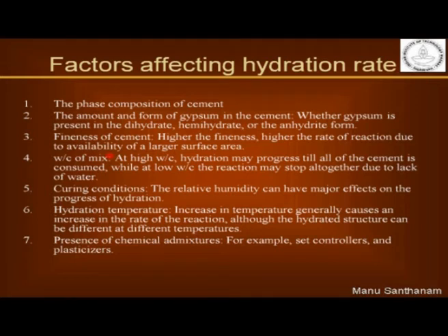Water cement ratio of the mix. Now I told you already about the rate of reaction with respect to water cement ratio. At low water cement ratio, your rate of reaction is much faster, but nevertheless at high water cement ratio, your water content is so high that your hydration may proceed for a very long time, because you have a lot of water available in the system.